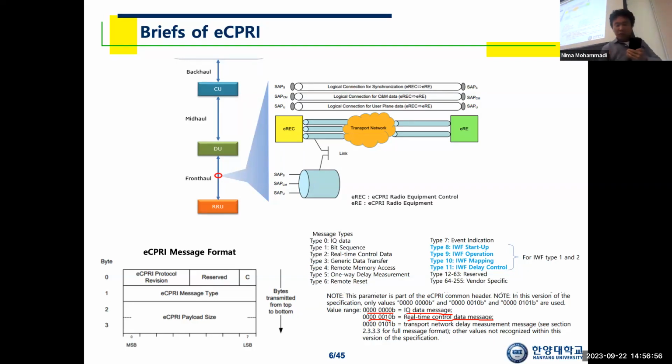Okay, what is that? What are user plane messages? What we want to transmit between ODU and ORU, from ODU to ORU for downlink, from ORU to ODU for uplink, is complex valued OFDM samples, right? So the real part and imaginary part of that OFDM sample are to be transmitted between ODU and ORU as user plane data. So just the I component and Q component of that OFDM sample itself is a user plane message. Okay? What is then a C plane message?